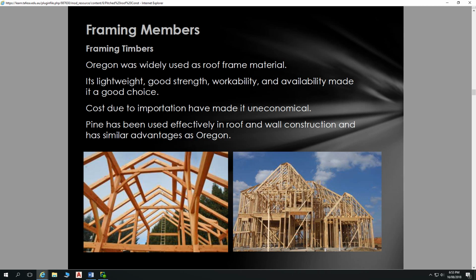Other timber species you'll commonly encounter in old buildings include jarrah. That's an Australian hardwood, an incredibly hard timber. Beautiful timber. A lot of the old jarrah has a lovely dark colour to it. You can't so much replicate that now, because that darkness comes from very old trees, and we're not cutting down very old trees anymore.